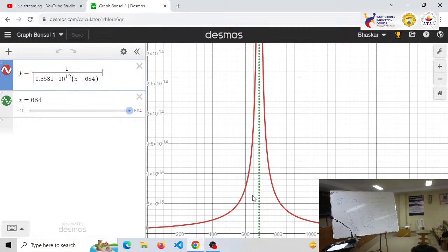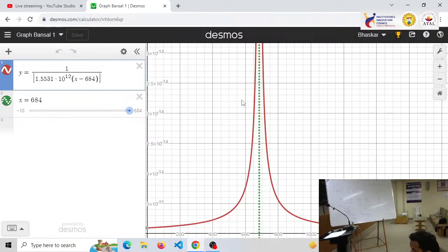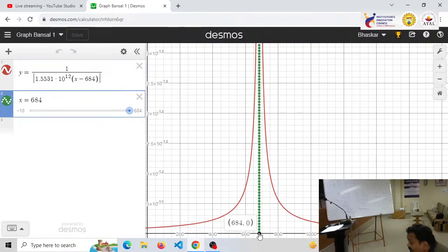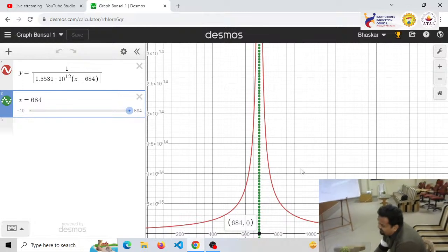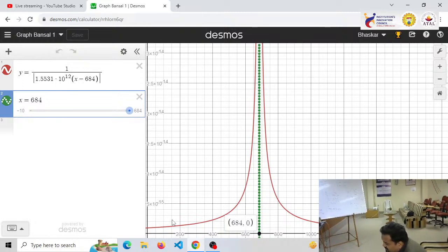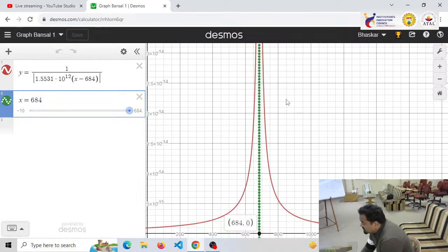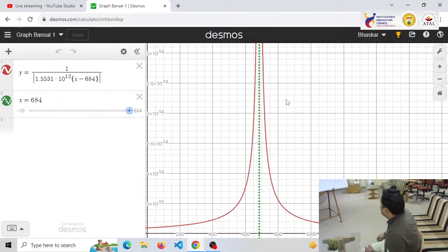So below this temperature, this is a ferroelectric phase over here, and this is a paraelectric phase over here. So at this particular temperature, the ferroelectric material is converted into paraelectric material. Till this temperature, your capacitance was increasing, and this is in ferroelectric phase. And now here the capacitance is decreasing, and now it is in paraelectric phase. So this was the graph number 1 for equation number 1, which I have derived over there.